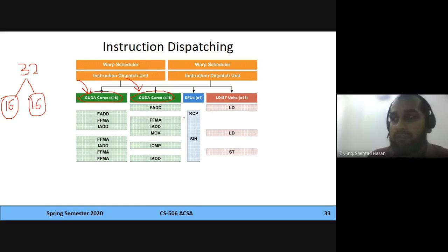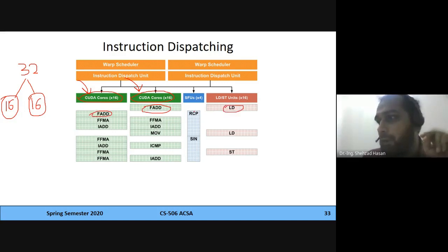If there is some special instruction that is going to be scheduled along with, you can have 2 operations starting every cycle. In this first case, what we are doing is floating point add and load together. Then we have floating point add and reciprocal together. Then a floating point multiplication and another floating point multiplication. Then we have addition and addition. Then a move and a load together, and then multiplication and sine started together. So we can schedule just 2 operations in every cycle, right? And then it's going to run that.